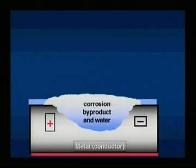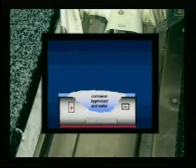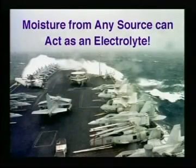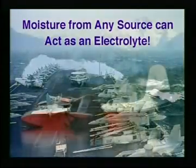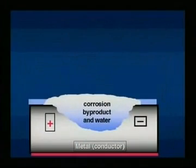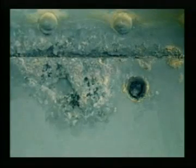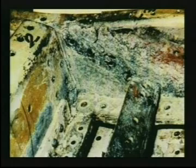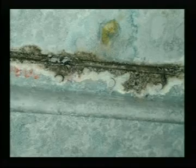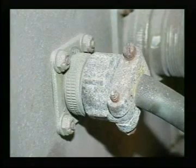Sources for these conductive liquids, or electrolytes, can originate as rain, humidity-induced condensation, soft drinks or juices, de-icing or toilet fluids, or even exhaust gas deposits that have been exposed to moisture. The corrosion arising from this contamination results in the metal slowly being converted or eaten away by the electrical current through the electrolyte. As long as the electrolyte is present, corrosion will continue to replace the metal with a powdery waste product.